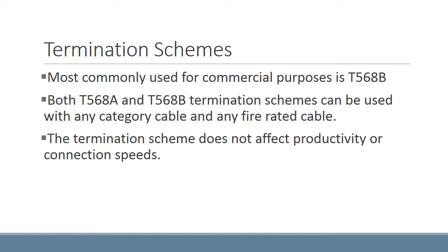The most commonly used termination scheme for commercial purposes is T568B. Both T568A and T568B termination schemes can be used with any category cable and any fire retardant cable. The termination scheme does not affect productivity or connection speeds.